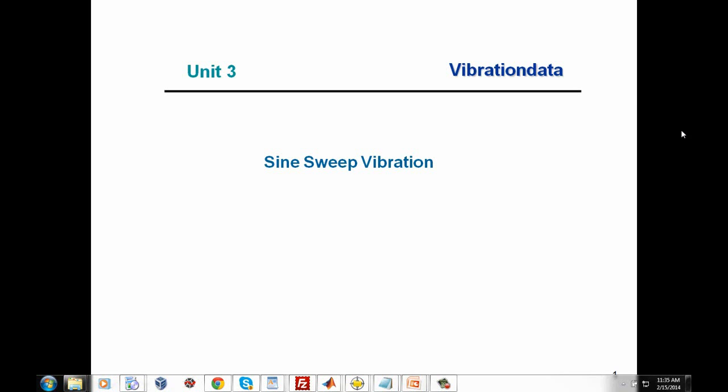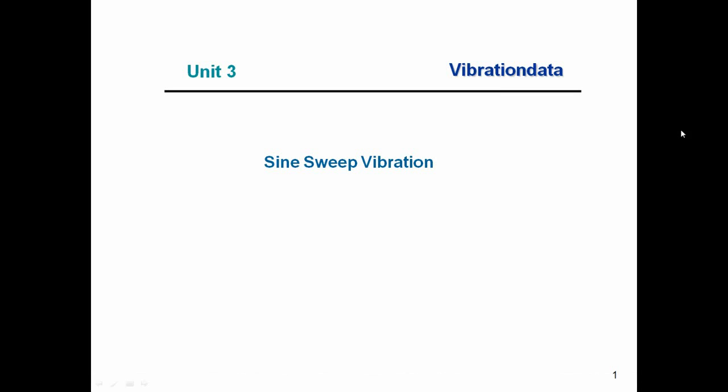So, why would we ever do a sine sweep test? Well, there's different types of situations. We might, for example, be doing a modal test where we have a small electromagnetic shaker attached to a test article via a stinger, and we could use a sine sweep test for modal testing.